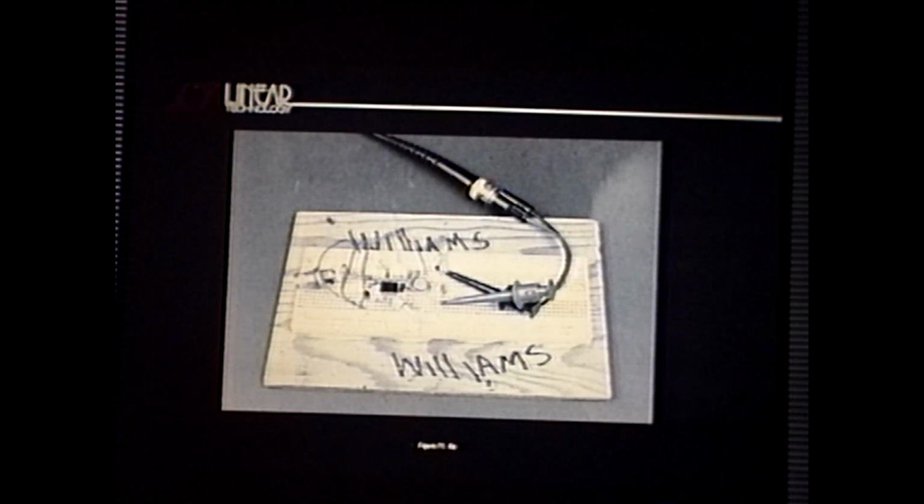And I went to some pains to say the breadboards do have to be gorgeous to work. But in a well-designed circuit, they only have to be gorgeous in a few spots. If you treat the highlights of the circuit correctly in terms of layout, you can save hours, sometimes even days, in the construction of the breadboard. You identify the circuit nodes where you've got problems. You treat those nodes very carefully, and everything else, you don't waste any more time than you have to to get the breadboard up and running.